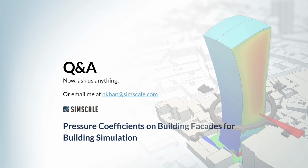You can just enter the location in the SimScale platform. For example, if the location is London, in the windrose dialog box, you just type in London, and it's like searching on a map, right? You can put in a postcode or a city, and then you click on London, and the data is populated automatically. So the windrose for London would automatically come in.